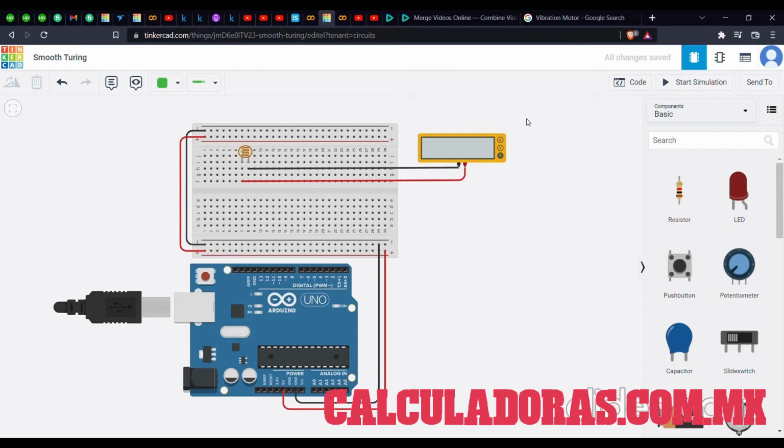So let's shift back to the beautiful interface of Tinkercad. Here is my photoresistor, and you can see it has two pins, terminal 1 and terminal 2. I have connected the first terminal to the positive of my multimeter, and this is the negative pin of my multimeter, and I've connected the second leg of my photoresistor here. Inside the multimeter I have chosen the mode as resistance. I could choose voltage, amperage, but I have chosen resistance.